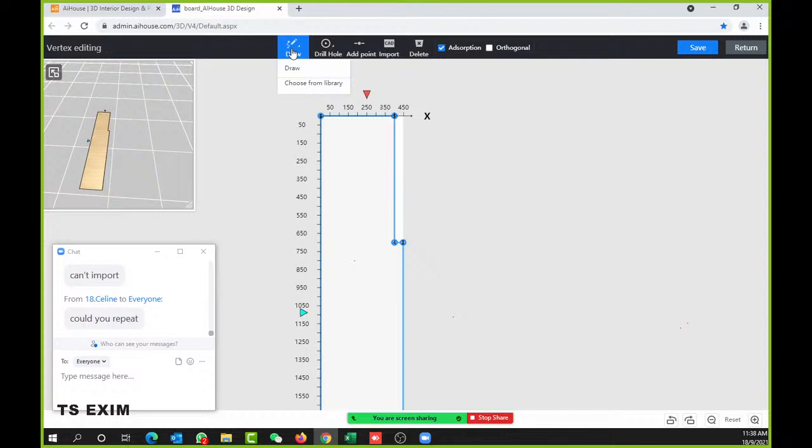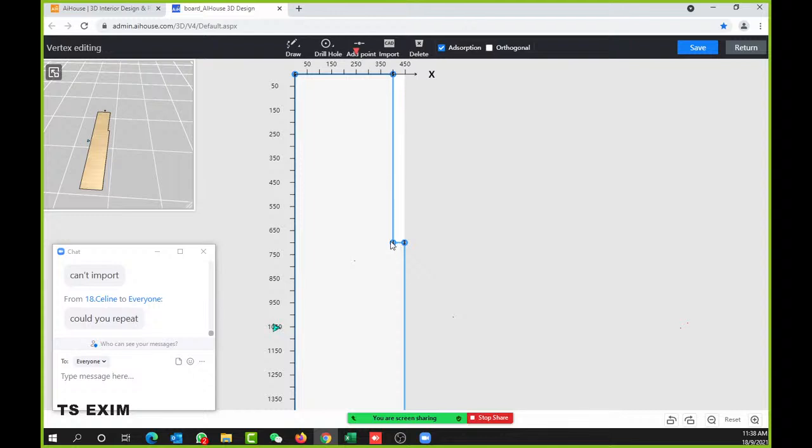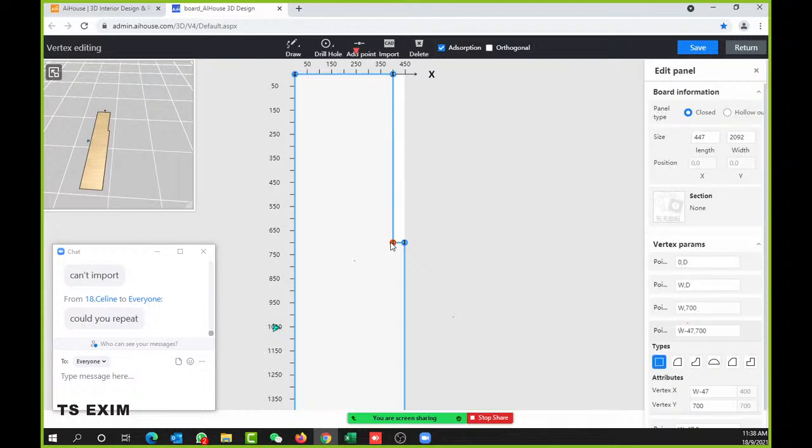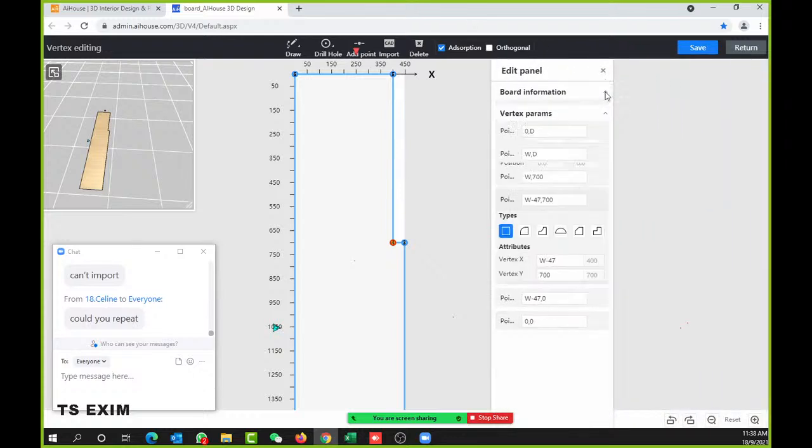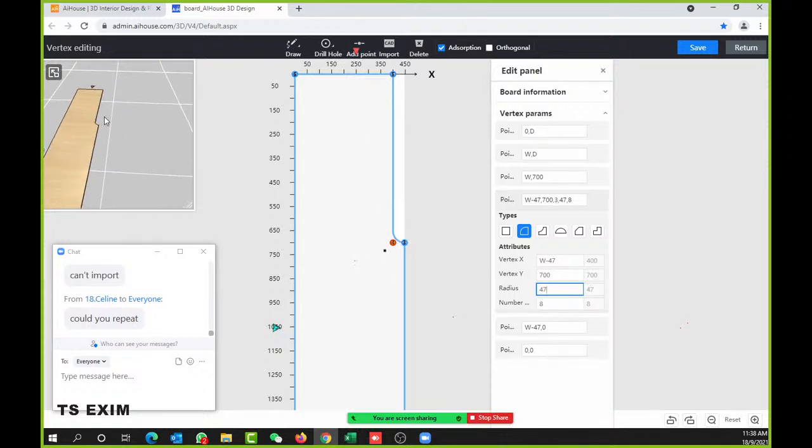Okay guys, time's up. So after that we do some pattern. This one is a handle, right? Maybe this one I do some pattern. You can click on number 4 here. This one we can change. Maybe I'll click here. So we hide it. The corner number 4, I make it outer fillet. The radius I make it 50. Then you can see some pattern for the handle.